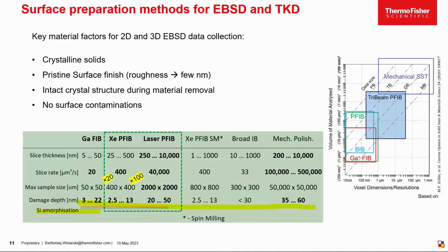methods in silicon. It is worth pointing out here that the range of damage is of the same order of magnitude, where FIB and plasma FIB are the least damaging. The literature shows that when the methods are properly used, all these methods produce surface suitable for EBSD, since the EBSD signal is formed at the few tens of nanometers superficial layer of the material.